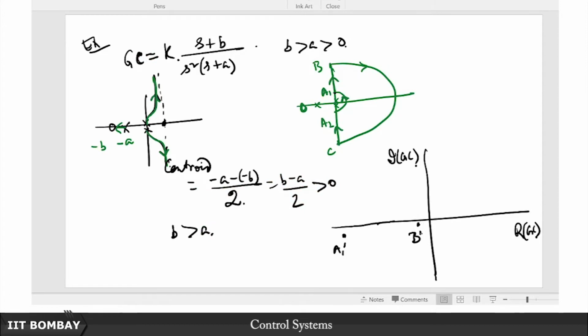Okay. So, this is our B prime, but now where will the difference show up? You see, now if you take any test point over here, say S1, what happens now? The pole contributes a greater angle than does the 0. And what does a pole contribute? A pole contributes a phase lag. So, effectively there is a lag, like the effect of one additional pole acting alone.